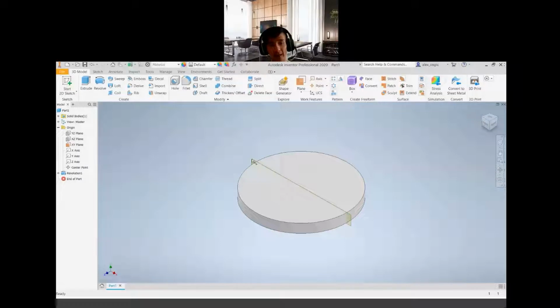So you see when you click in your drawing canvas here, you have this work plane here, which is visible. Okay, this is the browser. In the browser it will be like this. So when you go to your drawing canvas, actually it's not visible for your selection. So you need to go to the browser, select the work plane, then right-click and turn on the visibility of it.